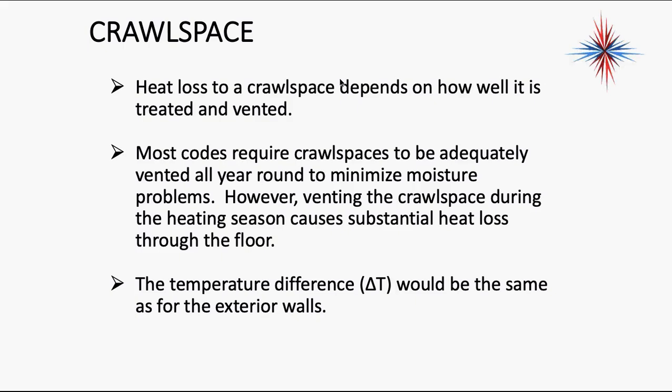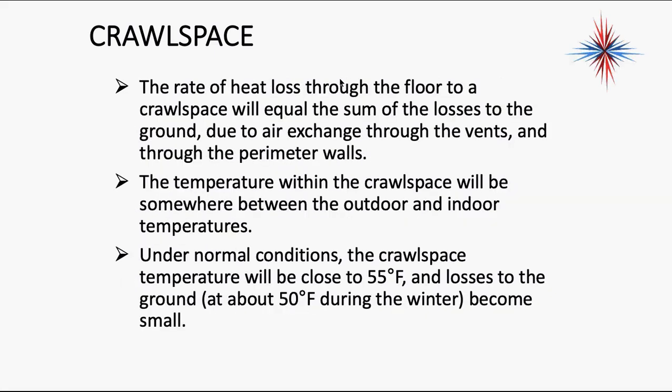Most crawl spaces, as it says, are not protected from the outdoor environment. They have to be vented. Air has to flow through them, or they start building up mold and mildew and other moisture issues. So crawl spaces, same difference as the exterior wall, basically.